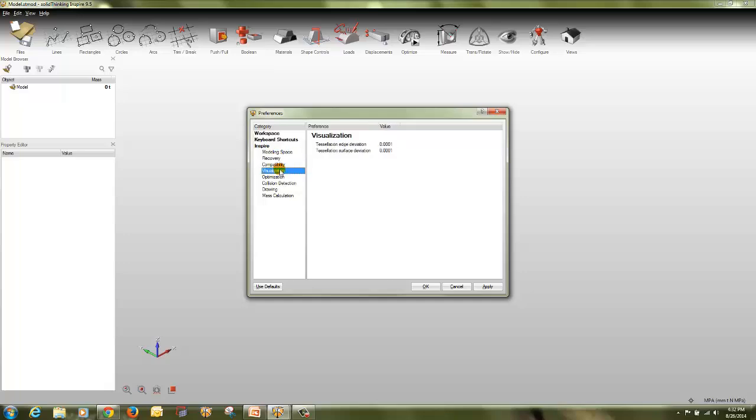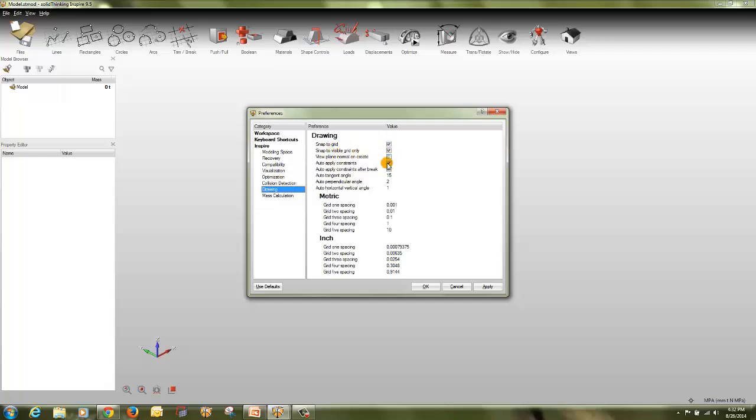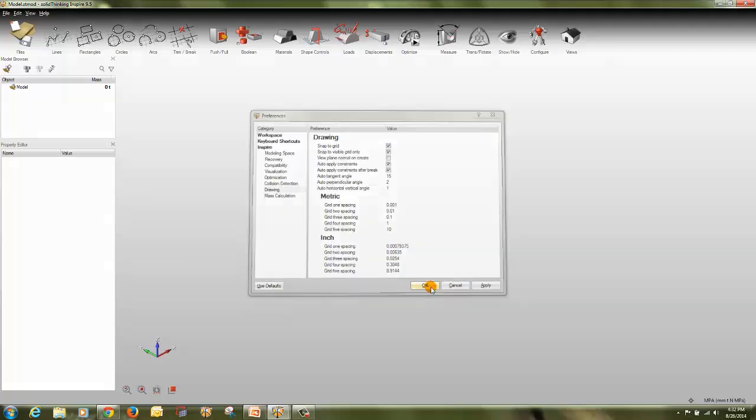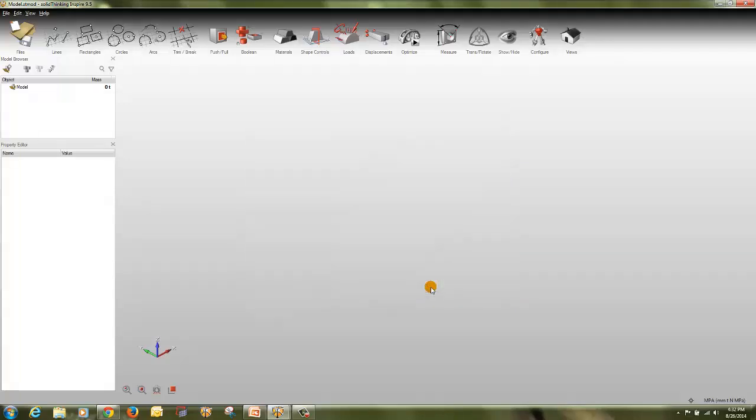Here we will see the snap enablement, snap to grid. If it's enabled, you can see this. If it's not enabled, you cannot see it. So you have to make sure that it is ticked, otherwise you will not see it. Then as you push or pull a face, it will automatically snap to snap points as you pass over them